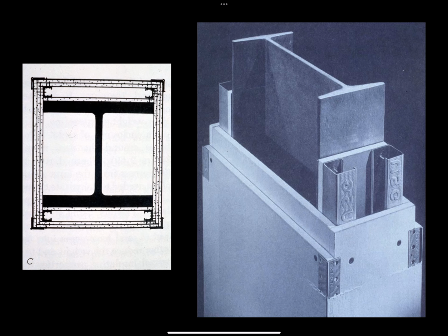You can have half-hour rated fire protection, 1 hour, 2 hour, or 4 hour fire rated protection. So clearly half-hour would have, in this particular case, fewer layers of drywall, and 4 hour fire protection would require more layers of drywall. So understanding this, the thing about the time and the thickness of the fire protection applies to all of these methods of fire protecting.